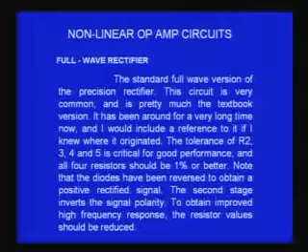Now the most important point is that you have to use the resistors we have seen in the circuit, R1, R2, R3, RF, all of which will have to be very precise resistors with a tolerance of 1% or even better. The tolerance of these resistors should be very good.